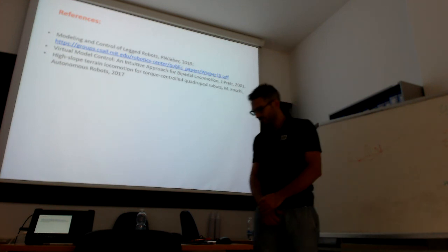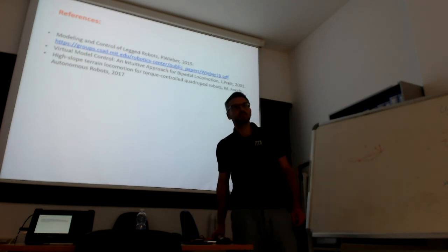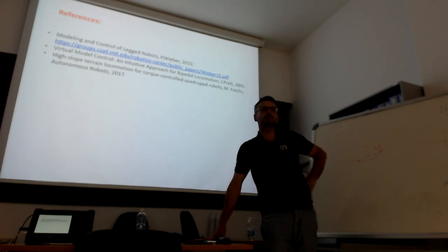Because, let's say, for dynamic motion, if the robot were to walk on a tilted platform, for instance, and it has to do faster motion, I believe that if the optimization were to calculate the trajectory, it might not have the cone constraint right in the middle, because it just needs to make a contact and disconnect very quickly and go to another contact. So I think this is a kind of motion you can see in Alex Winkler's dynamic motion, where it doesn't need to stay on the contact for long, so it just touches it and uses that dynamic motion.